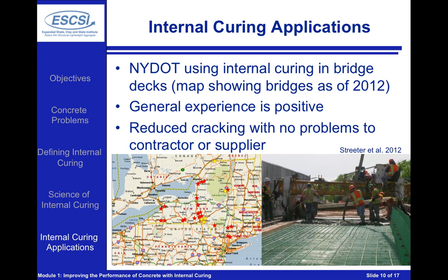So now, where are some of these different internally cured concretes being used, and where are they being applied? The New York State Department of Transportation has used internal curing in several bridge decks. In general, the experience has been very positive. They've seen a reduction in cracking with really no problems being reported by the contractors or suppliers. Here we can see a photo of some of these bridges being placed. We can also see the map that shows some stars of where these internally cured decks have been or are in the process of being cast.